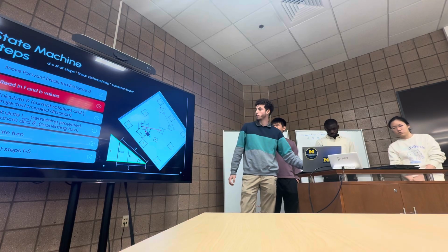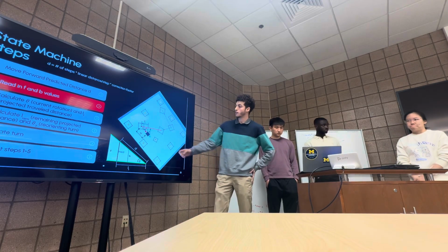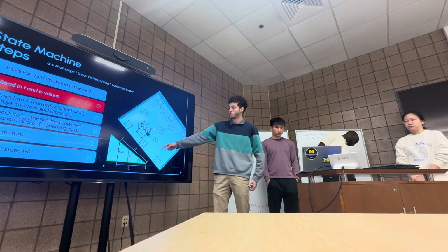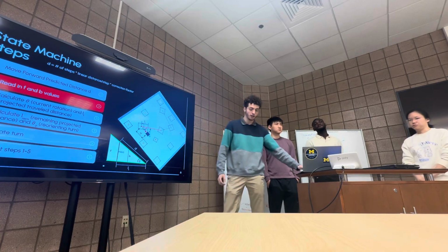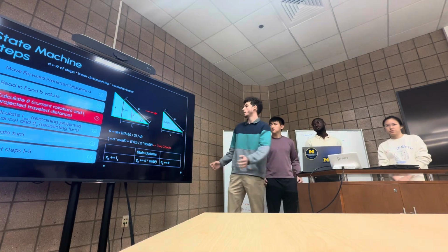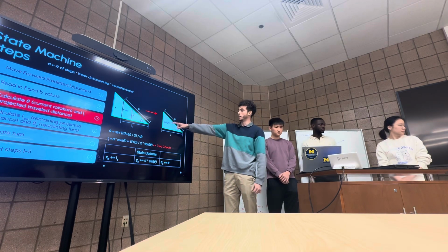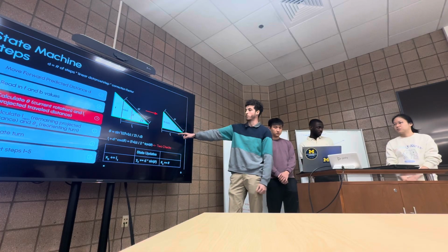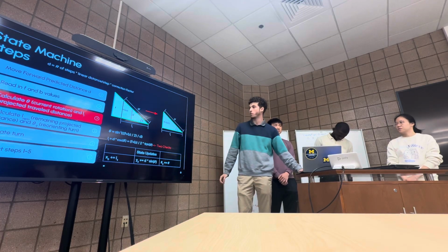Once we move forward, we'll get these F and B values, and then we can start doing some nice trigonometry. So the idea will be that the center of the robot is positioned in between the B and the F position. If you want to create a triangle, we can look at these two distances and find the midpoint between F and B. Once we isolate that, we can use the F plus B divided by 2 value and the D value to solve for theta and solve for L1. Once we get these values, we can update our states with everything that we've done so far.